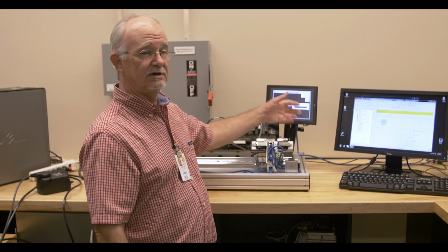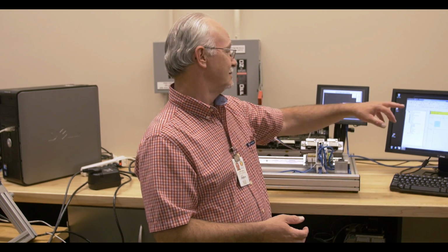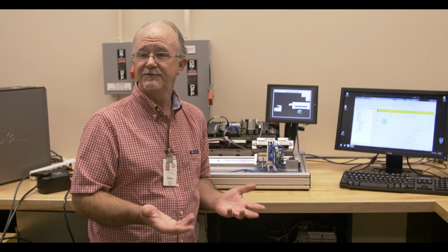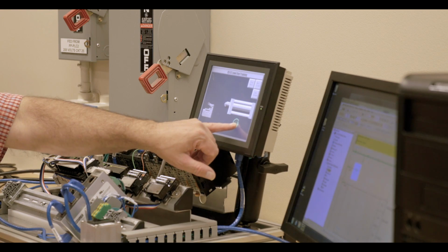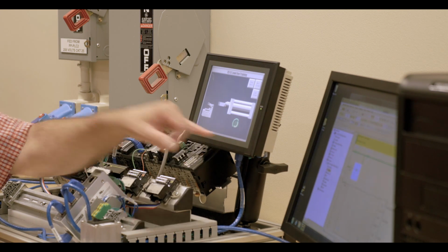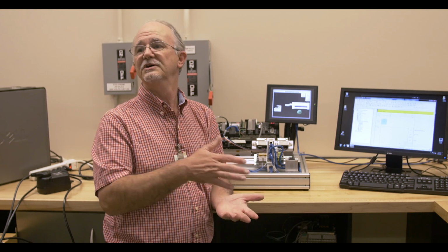What we generally do in the basic class is we start on Monday morning and we talk about the inputs and the outputs and the different kinds of field devices that we can have. And then we start getting into the actual logic programming itself. With the logic programming, we start simple, open contact, closed contact, and an output. So the first thing they do is they learn how to manipulate an output with a one-to-one relationship based on an input. And then we build on that.